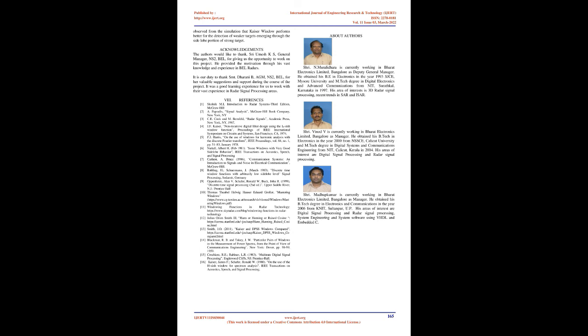Probability of detection and SNR calculation. Denote the range bin at which the single pulse SNR is unity, 0 dB, as R0, and refer to it as the reference range bin. Then, for a specific radar, the single pulse SNR at R0 is defined by the radar equation and is given by SNR(R0) = Pt G² λ² σ / ((4π)³ k T0 B F L R0⁴) = 1. The SNR is calculated for each range bin with the radar parameters shown above and listed below.